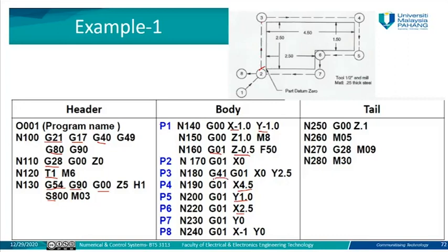All of this you can see here is G01, because all are linear profiling. Starting from here, G01, this one is also G01. The two previous, the main two parts here, just move to point number one. So the spindle here will move to the first point.